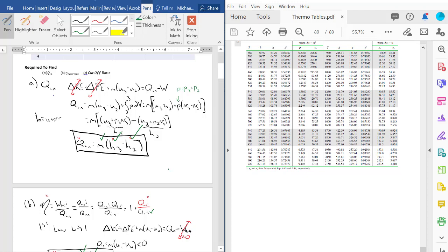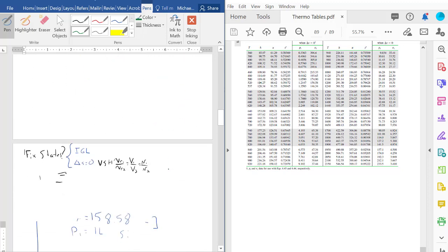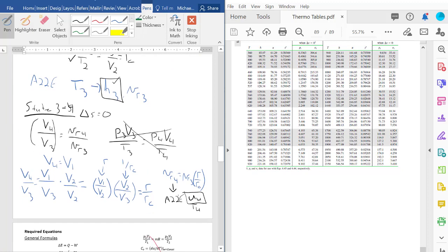But then the other thing that people mess up with the diesel cycle is this kind of sleight of hand that we did at the end, because you'll get to this thing when you're going between this process and you're like, I have no idea what V4 over V3 is. So you have to remember that there's this kind of magic trick that we can do to make V4 over V3, or sometimes this will be V3 over V4 if you flip it over, right? If it's V4 over V3, it's going to be the compression ratio divided by the cutoff ratio. But if it's V3 over V4, then that's going to be the cutoff ratio divided by the compression ratio. So I think this is one of the big tricks that people miss in the diesel cycle. And remember that the processes that are isentropic, you have special relationships for. I know we went a little bit over time, but I'm happy to answer questions if people have them.